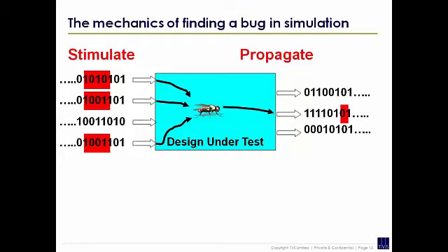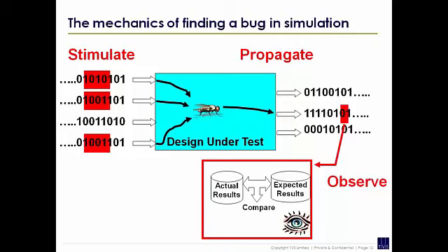Observation points are typically outputs, because we typically monitor outputs, but you can do white box and monitor internal signals, but typically it's black box. Typically you're looking at outputs, and you're monitoring and watching them. There's an eye there, but the last thing you want to do is do anything manual. I know people still look at waveforms, and that's a way of detecting a bug. If your bug works its way to a signal that's in your waveform, and the person watching it sees it, then that's an observation. But typically what you want to do is automate that observation.